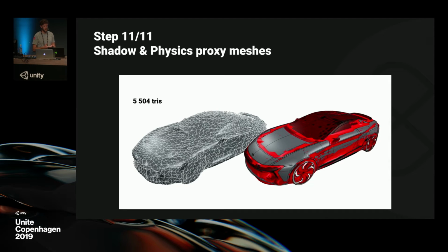In PiXYZ, we have what we call the Proxy mesh function. That's what we use here, and it automatically converts an industrial complex assembly like this one into a single wrapped envelope. So you switch from thousands of parts and millions of triangles to a single low polygon model. That's what you see there. And we have other remeshing algorithms, so Cédric will show you the other ones we have.